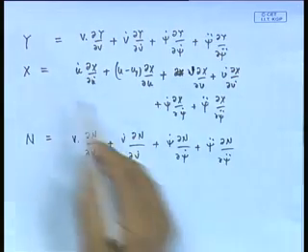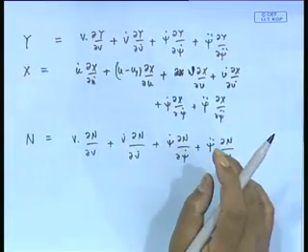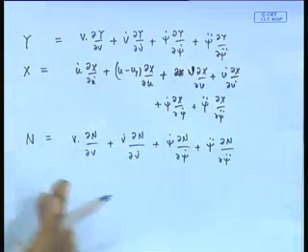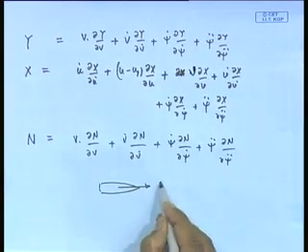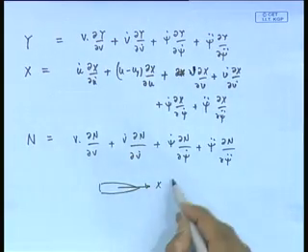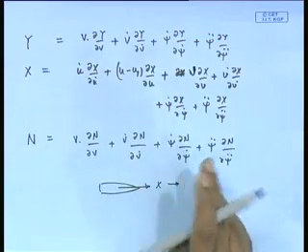See, now I will tell you what we are going to do. We are not going to look so much on the x equation. The reason is because the x equation shows how there is a force on this side. So this force is going to cause motion in the x direction. Instead of making a constant speed, it might be perturbing on that. Say instead of 10 knot, it might go 10.2 knot, etc., which is of not much interest for us from the maneuvering point of view.